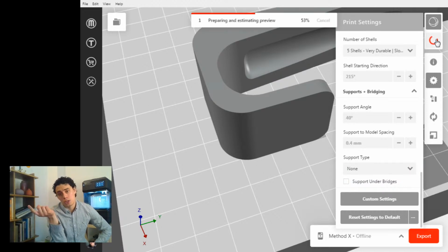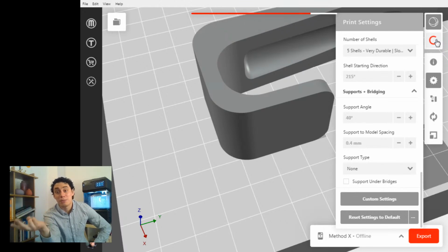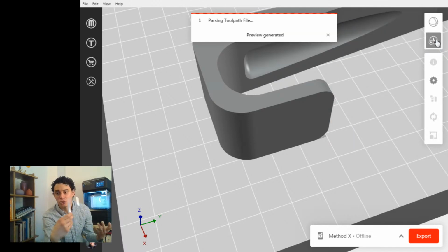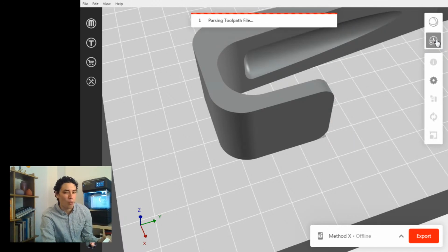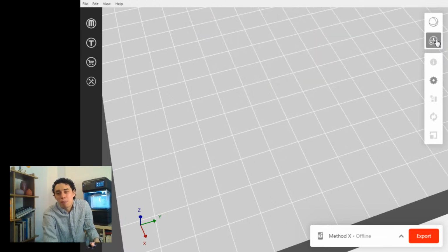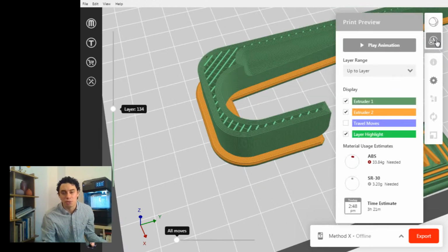And this is going to do two things. First of all, it won't create supports, and because of that, you will save a lot of time. Ideally, when you're just drafting the idea, when you're just testing something out, you don't really want to have supports, or you want to have a part that's simple enough. It's not always possible to do a part that will not require supports.